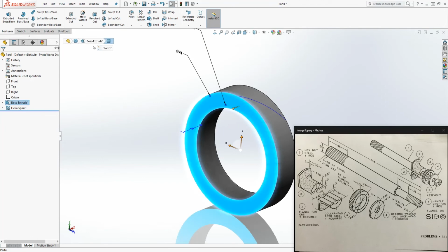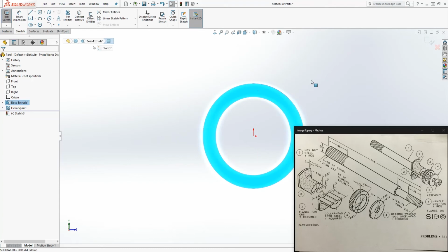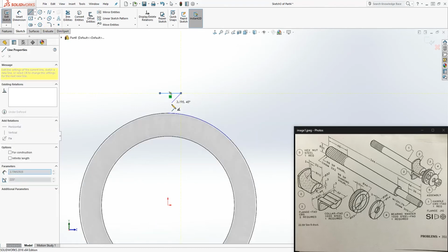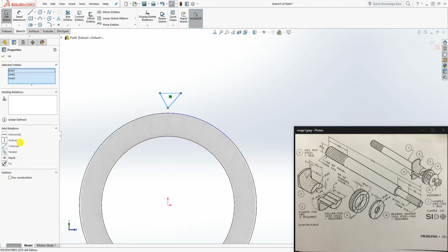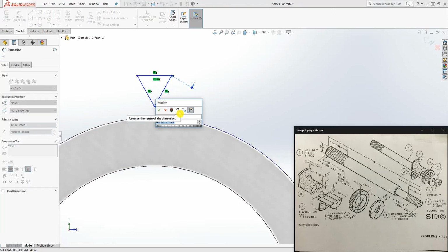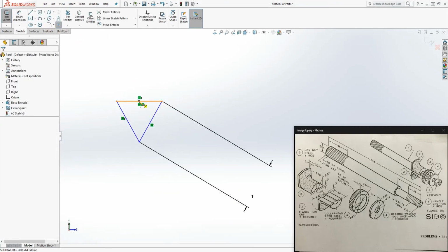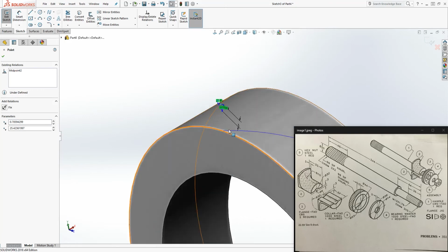So again, we click this face again, sketch, number 2, and we are going to draw 3 lines again, something going like that. Holding the control key, select all those lines, make them equal to each other, add a dimension of 1, and you can put a point on the midpoint of that top line, and select that point. You have to kind of zoom this, move this down a little bit so you can see your helix. Select your helix and pierce it.